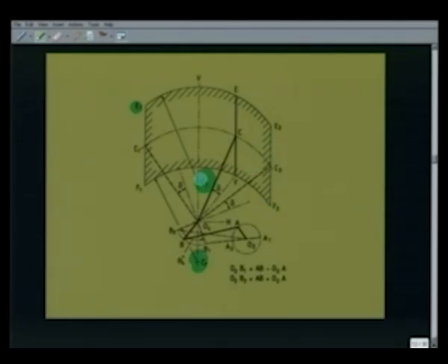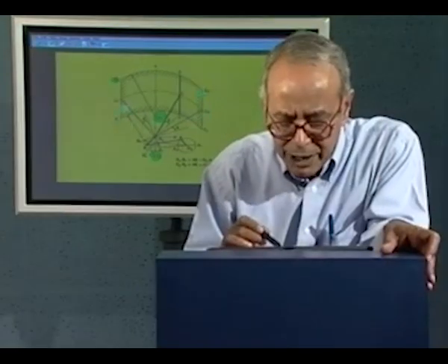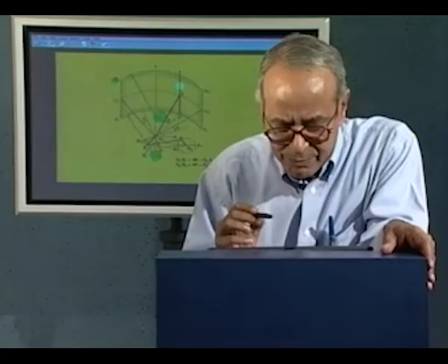That is, CE-CF is the same as E2-F2 and E1-F1. So, with center as CE and radius as O4C, which is the same as CE-E1, I draw this circular arc. Similarly, with center as CF, I draw this circular arc, and these are the two extreme positions, and the wiping field is what has been shown by these hatched lines. So, we have obtained the field of wiping for this particular mechanism.